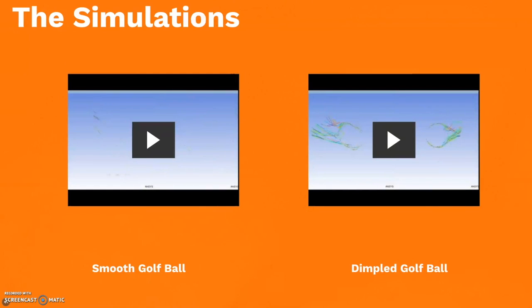We managed to create simulations for all 3 golf ball designs, with the smooth design and the circular dimple design being shown here. In these videos, we have the simulation being viewed from the XY plane and also from an isometric point of view. Using the simulations for these 2 designs, we were able to get a clear indication as to what was happening in terms of the turbulence experienced by the golf ball, the resulting wake region, and also the overall pressure distribution along the golf ball.